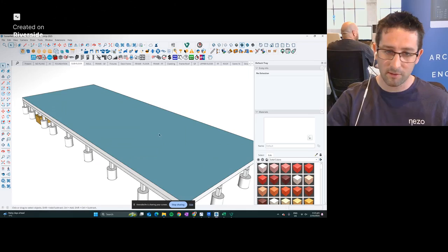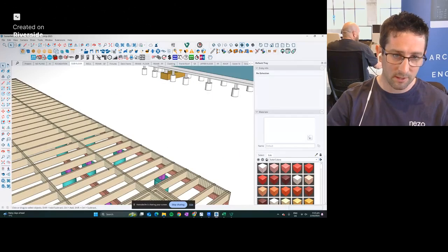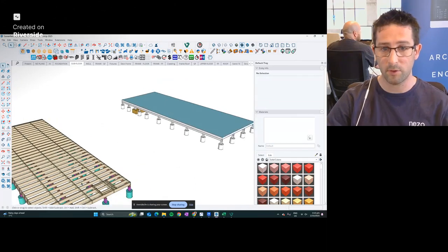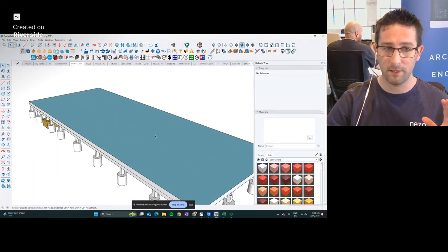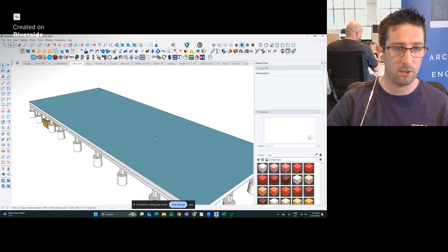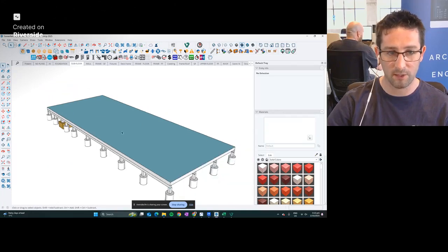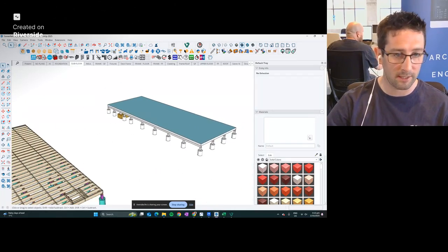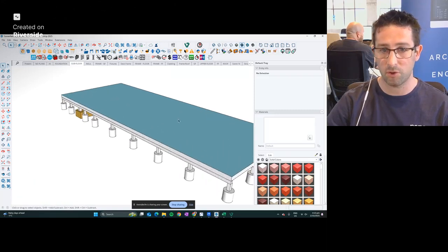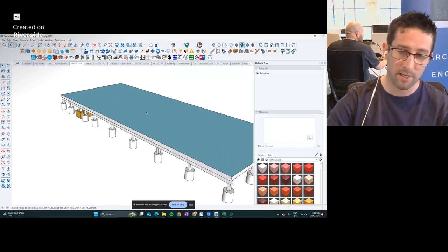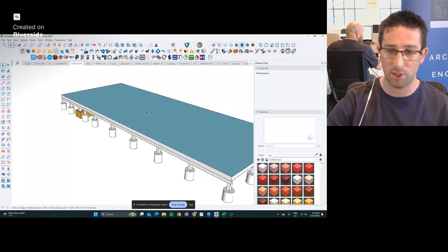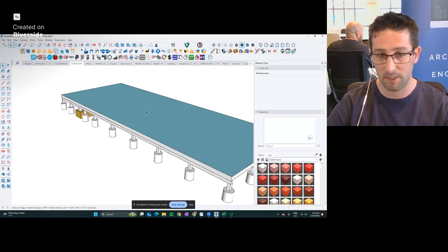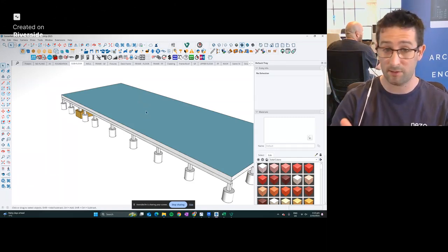So you can still access the specific carbon data for each EPD that you would find in Nezo now inside of your Revit or ArchiCAD, but with the Nezo materials, we can use cubes and squares and still quantify all of that material, but very, very quickly. Instead of modeling that floor, I can simply draw a rectangular slab, apply a Nezo material, and I'm able to generate all the quantities for that insulation, for that concrete, for that treated timber. And when I export out, that takes 30 seconds.